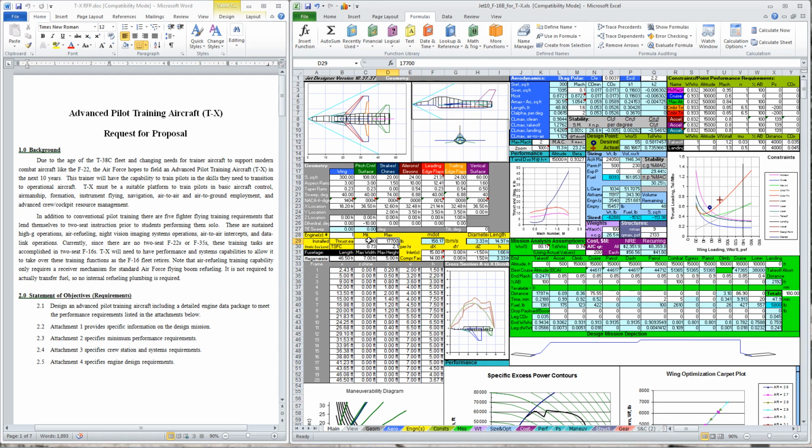So we model that by putting in the appropriate maximum thrust. Thrust-specific fuel consumption is very similar. And at this point we say, yeah, we still have plenty of engine. But notice what a huge gain that gave us in terms of weight. It's a smaller, lighter engine. We can reduce the weight of the aircraft commensurately. Also, the smaller engine burns less gas on the mission, so we can drop the weight at least to 21.8.